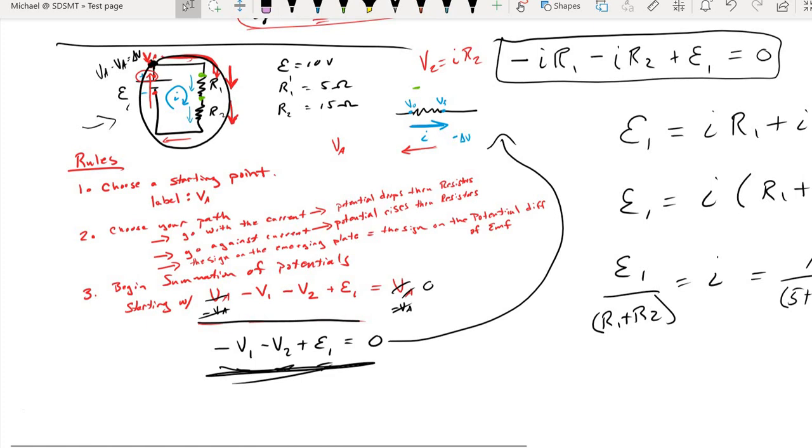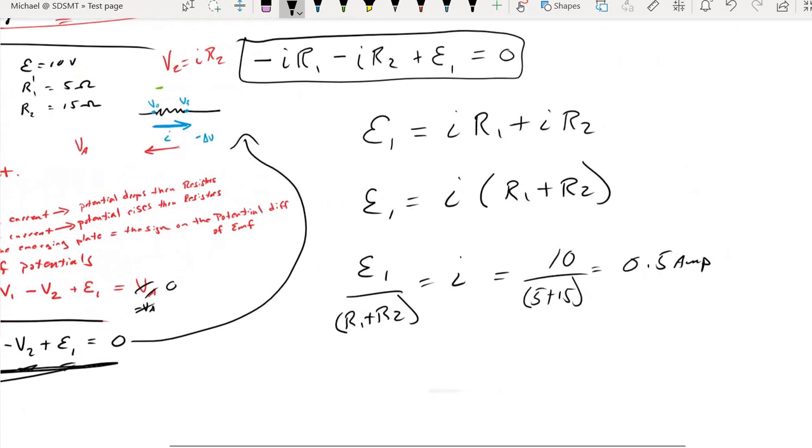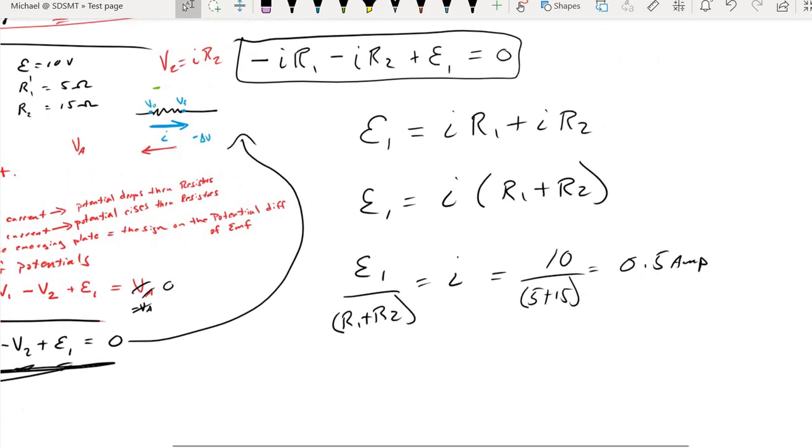And when I first drew this circuit over here, you were probably saying to yourself, "Oh, that would be a really simple series circuit. I could make an equivalent resistor out of that, and it wouldn't have taken me nearly as much time as what we're doing here with Kirchhoff's law." And well, that's exactly what happened, because with series resistors, how do you get an equivalent resistance? Well, you just add the resistors together. And so we quite literally reproduced the series equivalent resistance example.